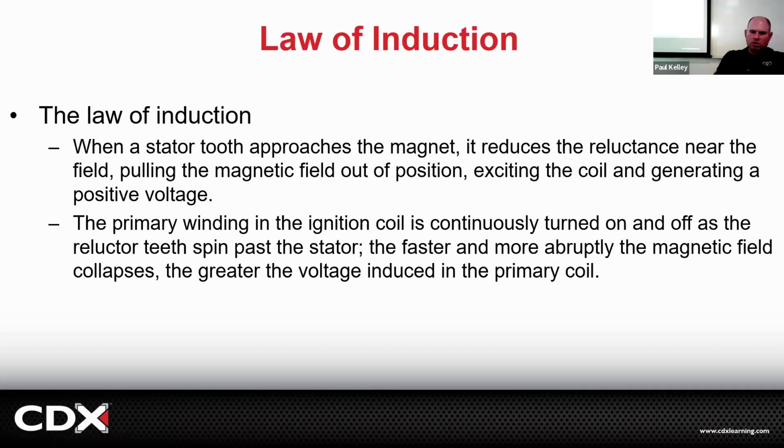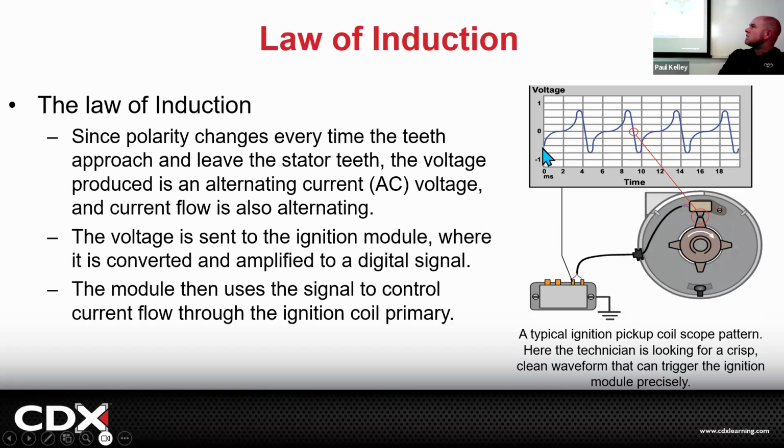So you're like, what? Let me just give you a preview. You see this waveform? It started negative, went up and up and up, and then it dropped away. That's as this tooth right here gets closer to that sensor. This sensor is going to give a signal to a little module, which a lot of times we'll call an ignition pickup.